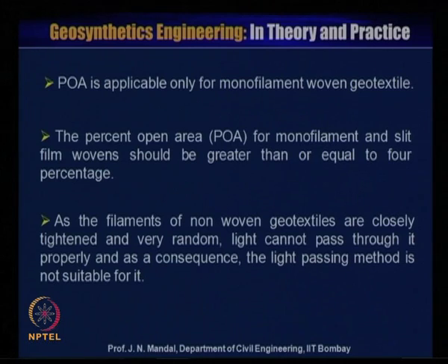Now, POA is applicable only for monofilament woven geotextile. The percent open area POA for monofilament and slit film woven should be greater than or equal to 4%.